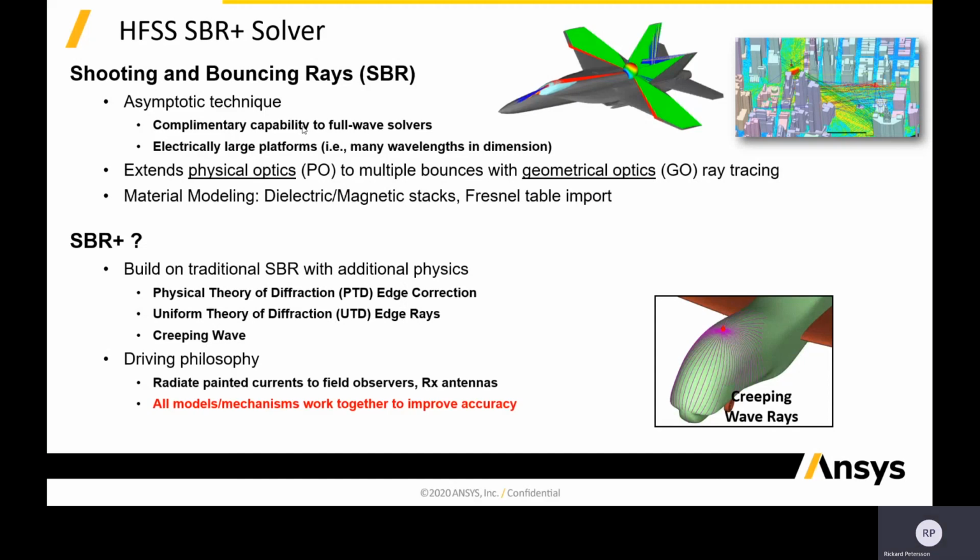So the driving philosophy of SBR+ is that we radiate induced currents to field observers, and all models and mechanisms work together to improve the accuracy. So SBR and the PTD, UTD, and creeping wave, if they're all used, they all enhance the accuracy of the solution.